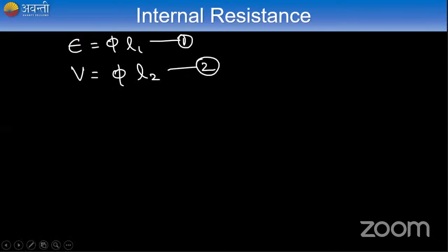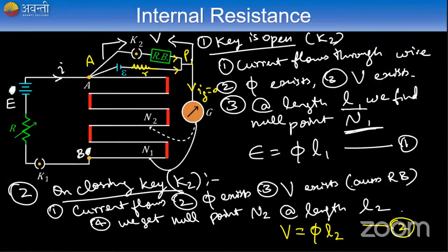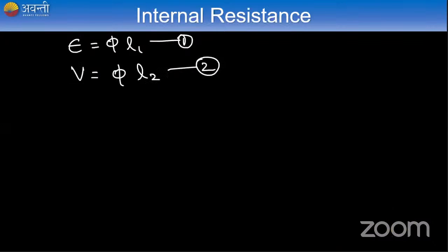So guys, now if you see here, there exists a common current I. Why? Since the current through the galvanometer, IG, is going to be 0, there exists a current I. How much is the value of this potential V? How can I write the value of V? Can I write it as the current I flowing through the resistance box R, using Ohm's law? Can we write V is equal to I into R, where R is the resistance from the resistance box?